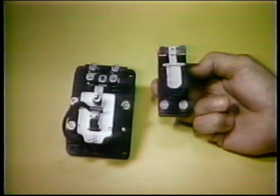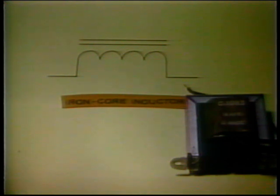Inductors are classified according to the type of core on which the coil is wound. The type of core used in an inductor is important because it affects the strength of the magnetic field around the coil. All electromagnetic relays or applications requiring a strong magnetic field employ iron core inductors. An iron core inductor is represented schematically by a coil symbol with 2 lines next to and parallel to the axis line to indicate the presence of an iron core.